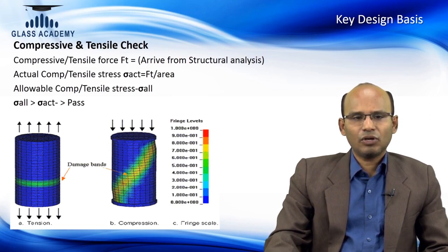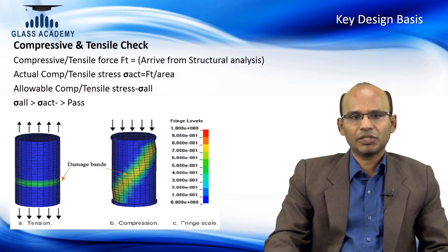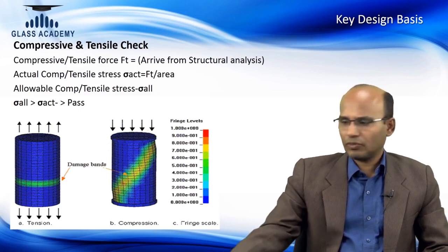This is critical for a large element, or maybe sometimes the framing is used continuously for quite a number of floors. There, compression is critical, as a structural engineer knows, when certain elements are weak in slenderness ratio. So, as engineers, they have to check the slenderness ratio. If that falls under semi-compact or slender, then this more detailed check is required.